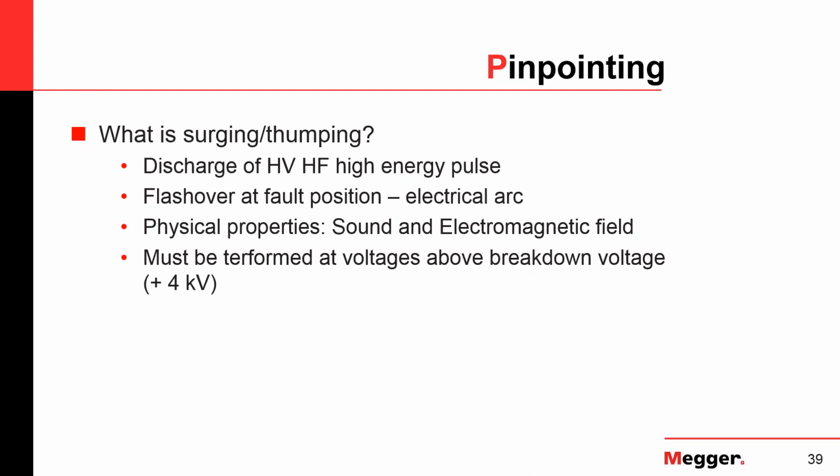So what does this pulse do? Well, it travels to the fault position. There it flashes over. This is why it's important to thump at a voltage above your formerly learned breakdown voltage. Otherwise, it won't flash over.